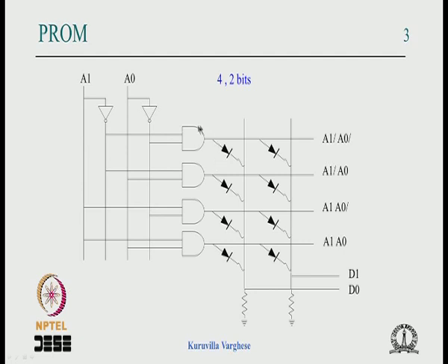So the moment we decide we can use fewer AND gates, we would definitely make these AND gates programmable, and at that point we are not working with minterms, we work with product terms, which further reduces the number of AND gates required. That was the next step. People started building these devices from the idea that the PROM is too much of an overkill.